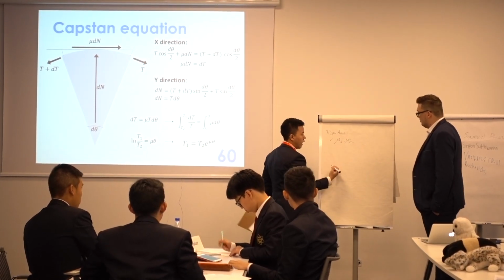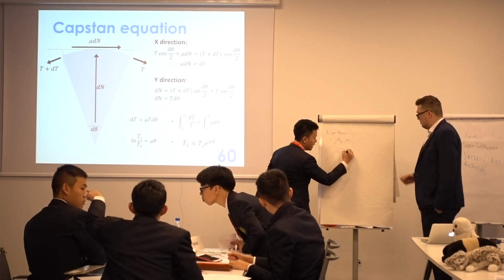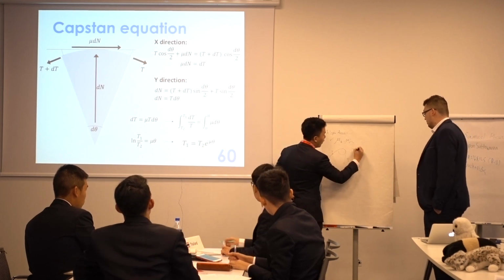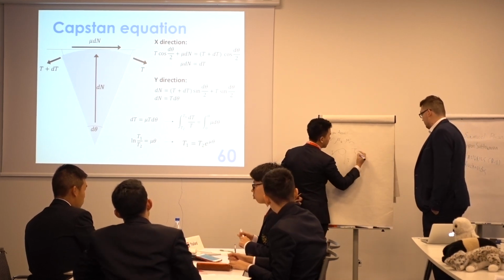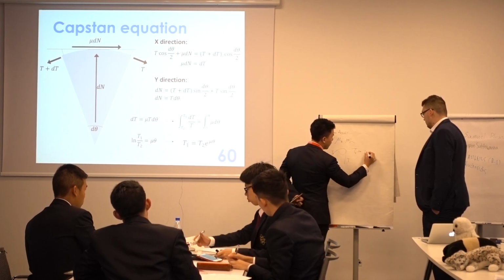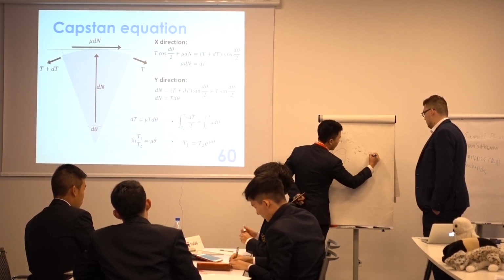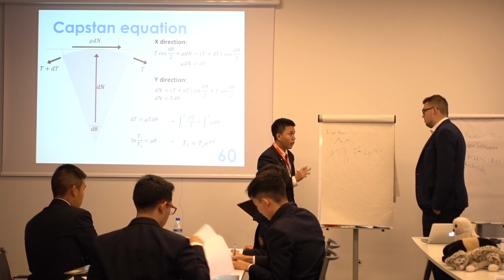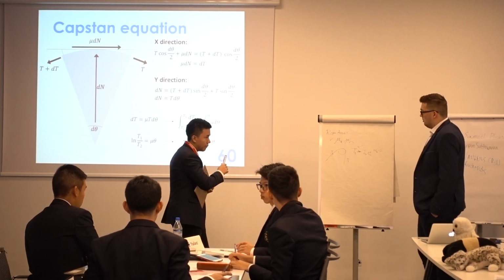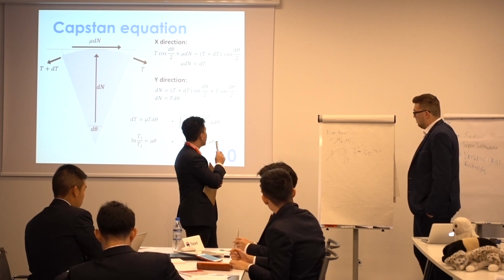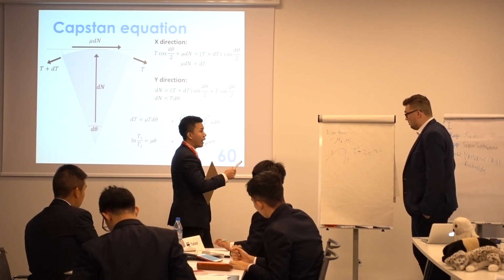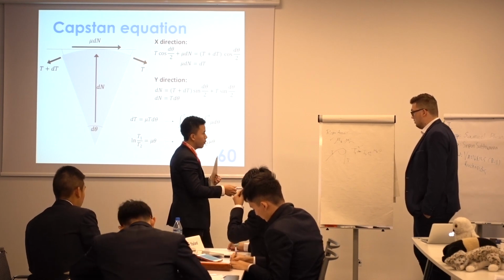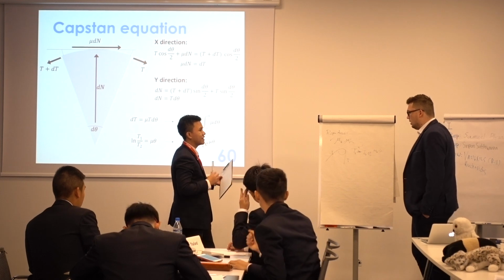And on the next part, where the rope is not sliding, the tensions T1 and T2. When the rope is not sliding, I think the tension on this part does not have to be on this side. So what I'm saying is that the condition of the capstan equation is that it is about to slip. That means it's using the maximum static friction. But during the stop of the simulation, the static friction does not have to be at its full value. Do you understand? I'm not sure.